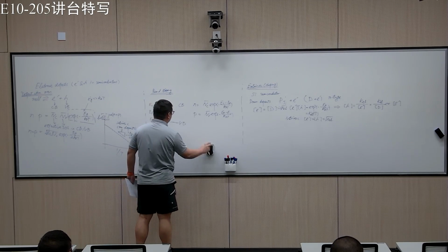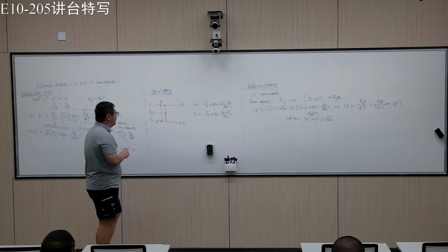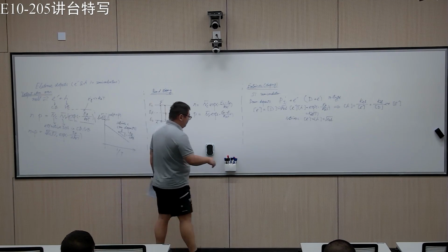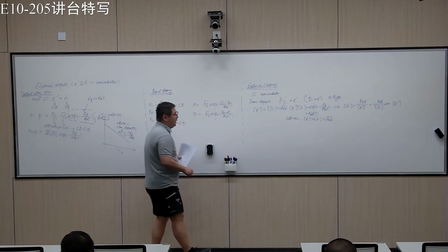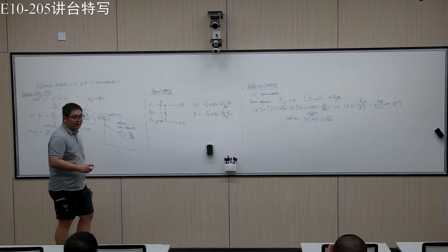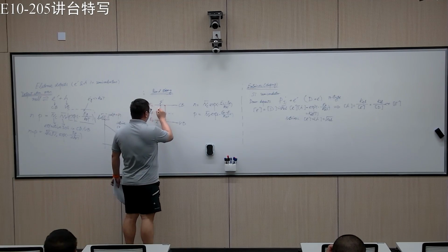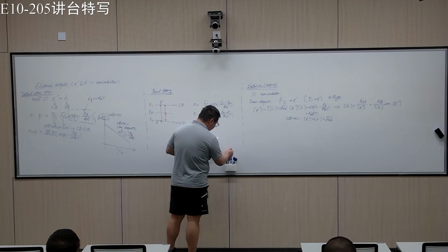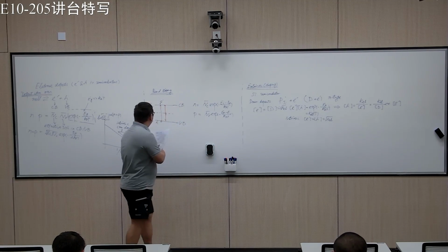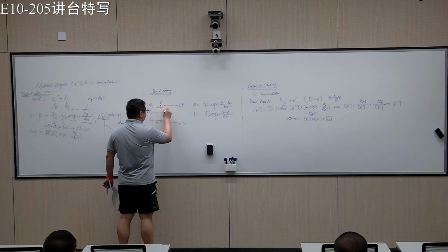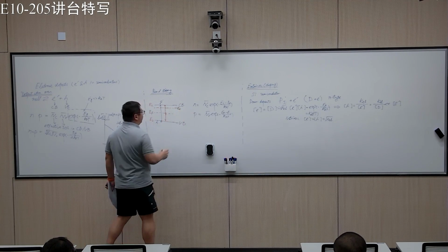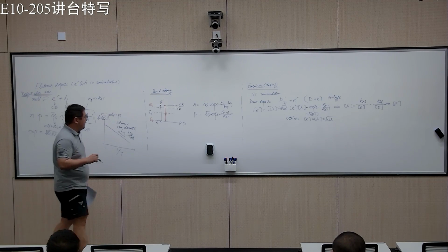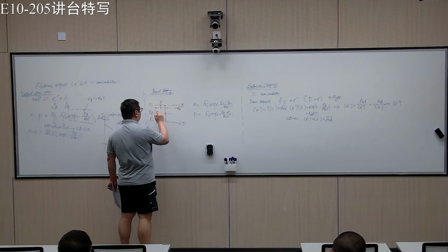So in terms of band theory, if we put a dopant in, we are going to introduce a dopant level called ED. Basically, that's still within the band gap. And what it does is move the Fermi level to here.